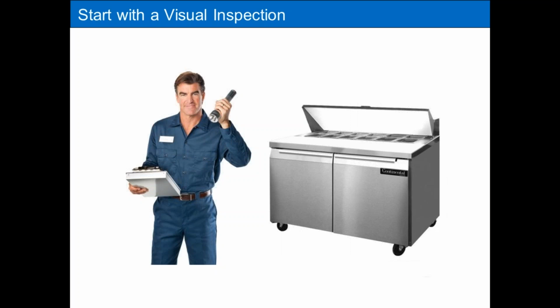You look at the condenser. Is the condenser dirty? Look at the evaporator fan motor. Is it running? Because it's supposed to be running all the time. Is the evaporator iced over? Are the gaskets falling apart? Are the door hinges damaged? Look for the visual problems that could cause you and your customer some grief. Don't make any upfront decisions. Just look. Spend 5-10 minutes just looking around.